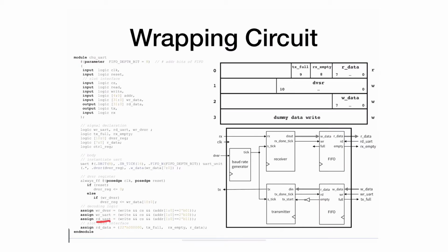Interesting. What does the read UART do? It's actually this dummy here. We'll see it shortly. So let's see what the WR divisor is. The WR actually goes and tests, am I in offset number 1? Because this is offset number 1. If that's the case, I'm going to enable that signal, and this signal actually led to the write of that particular value that the processor wanted into this particular divisor register in here.